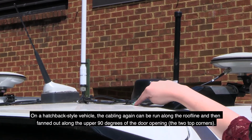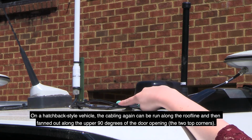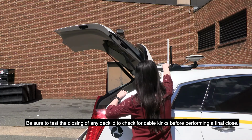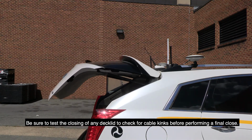On a hatchback-style vehicle, the cabling again can be run along the roof line and then fanned out along the upper 90 degrees of the door opening, the top two corners. Be sure to test the closing of any deck lid to check for cable kinks before performing a final close.